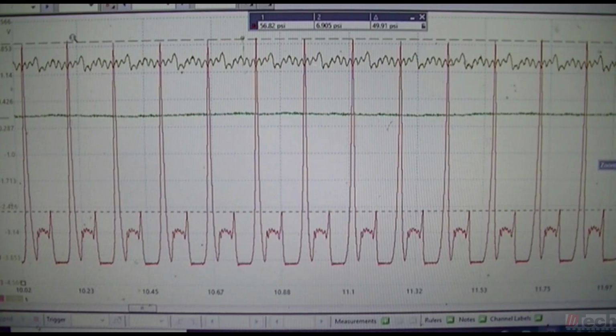Okay, so now to bring up the captures from the idle, this cold startup idle with no oil control valves plugged in. Basically, we are going to start up and let it run idle with no intervention from the variable cam timing system on both banks for both intake and exhaust, and see what it looks like running just on straight up timing chain installation position, just like we did when cranking.